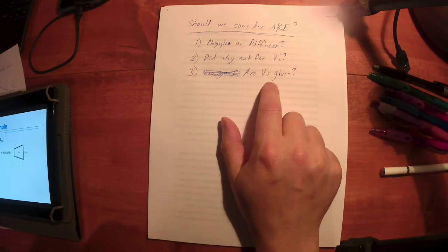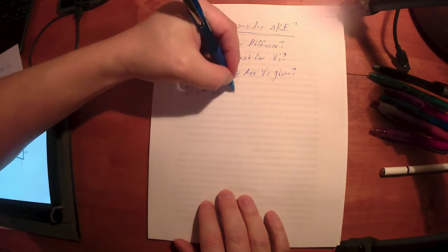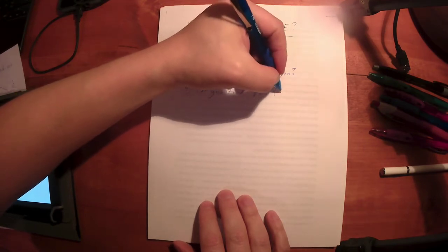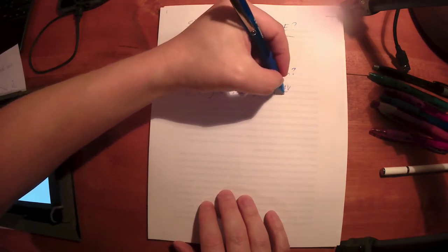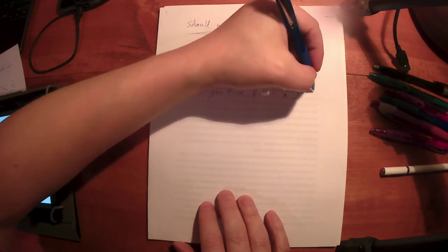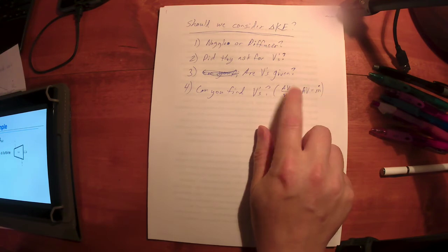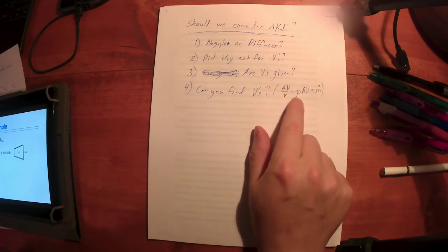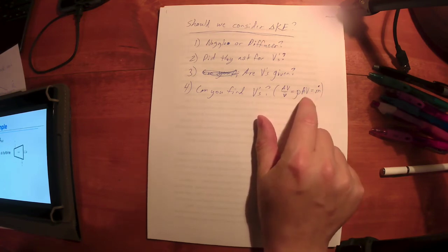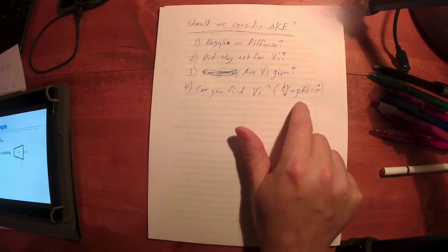Okay? And then the 4th thing is, can you find the speeds? Right? And normally that's going to be AV over the specific volume is equal to the density, AV, which is equal to m dot. So basically this is kind of the best tool you're going to have to find a speed if you know the area at the inlet and or the outlet, and if you can find the specific volume or density, to find the mass flow rate, or given the mass flow rate, find these other things. If you can find the speeds, and this is not the only tool you could use to find the speeds, but it's the most common tool to find the speeds.